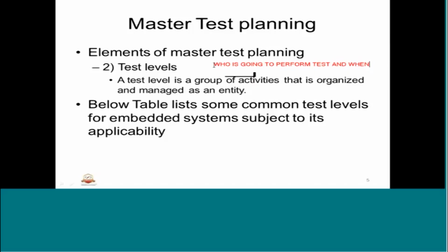So we'll start with the small subsystems and components, then we'll grow up with the higher incremental testing. Finally, we check if they conform to the higher level requirements intended for that particular embedded system. And we know about low level testing and high level testing. Low level testing focuses on isolated components executed early in the life cycle, in the bottommost part of the V model. High level tests are tests on the integrated systems or subsystems executed later in the life cycle, on the right hand side of the V model. It could be simulated or target based, etc., based basically on the real life environment.